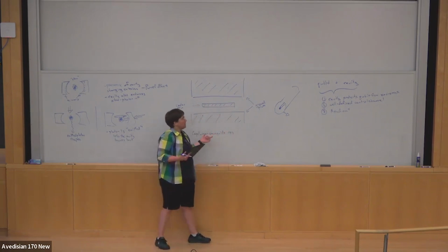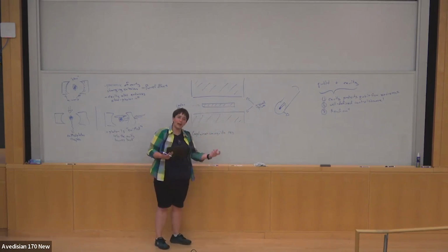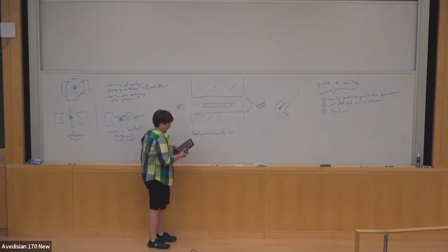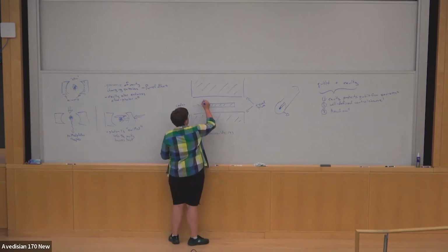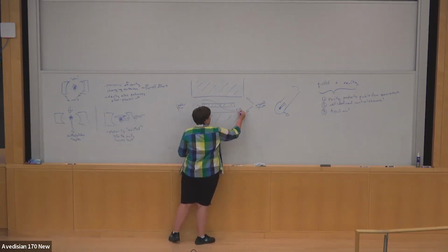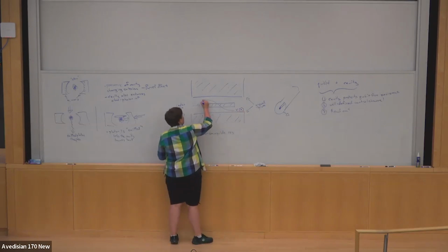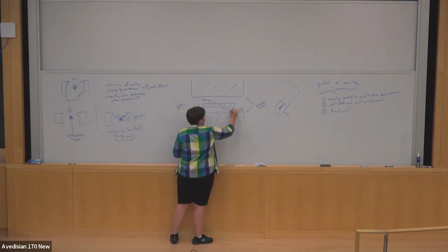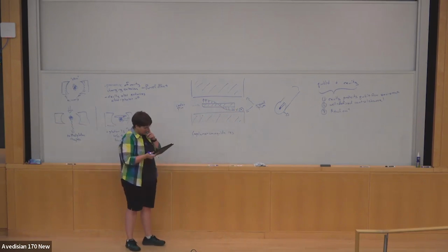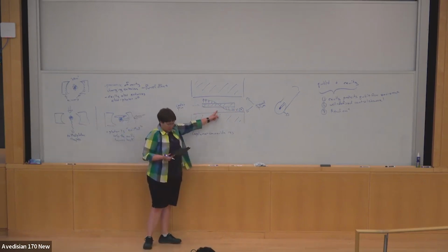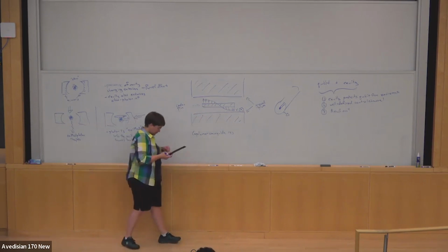And so this is the same kind of resonance that you would get in a finite piece of cable, but you can fabricate it in 2D out of superconducting film. And so the standing wave mode that lives in here has a voltage profile that looks like that, and the electric field is oscillatory and points out from the center pin towards the ground planes or vice versa. And so this is the kind of resonance that we typically use.